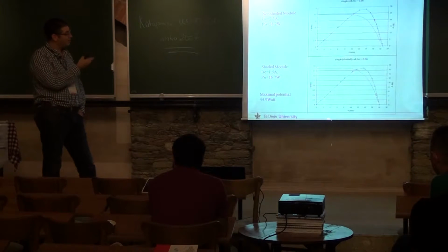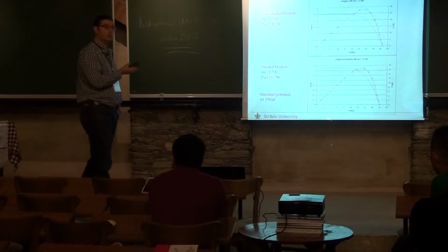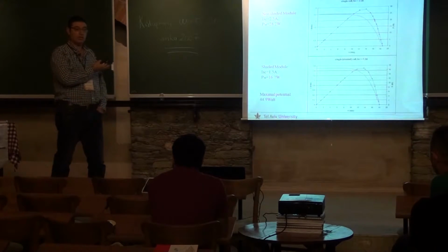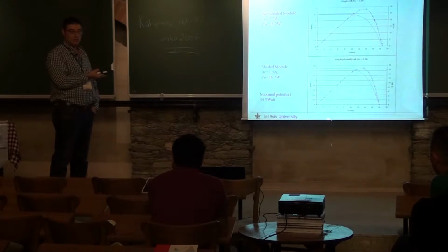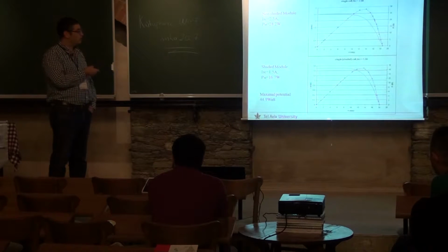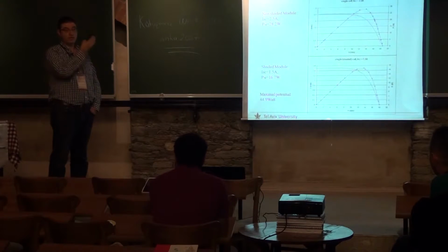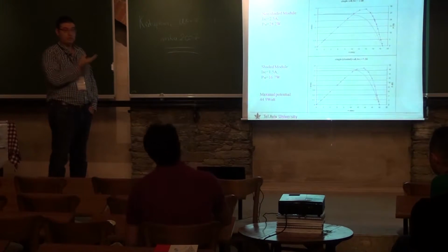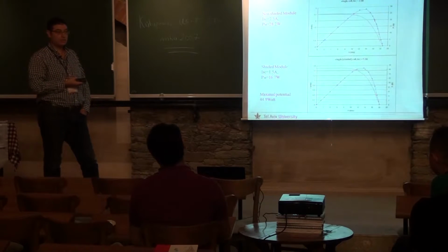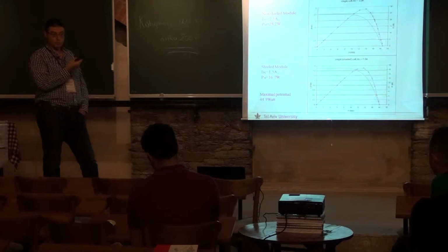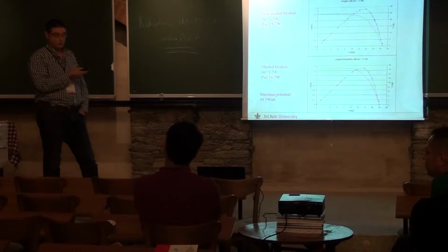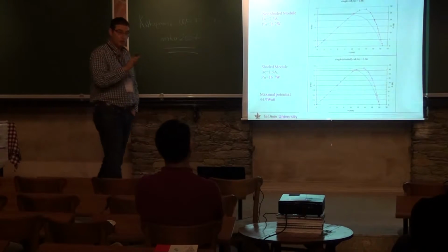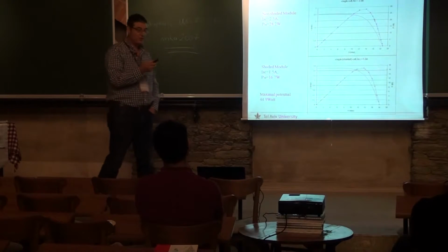So calculation indicates about 2% losses. In practice, we had 3% losses. But you see, this is not a typical case in the sense that we only have just 2 modules. If we had 10 modules, we would be really close to 100% efficiency because we don't process the power actually. Because let's say, the best power processing is no power processing, okay?